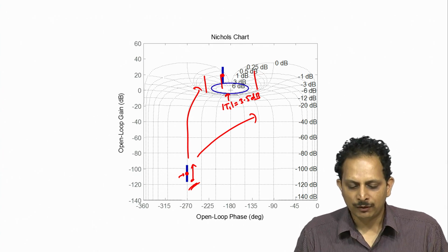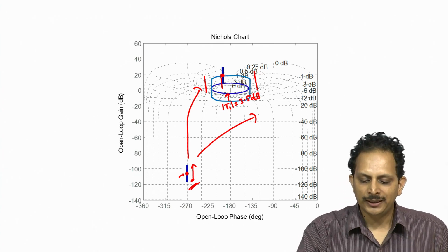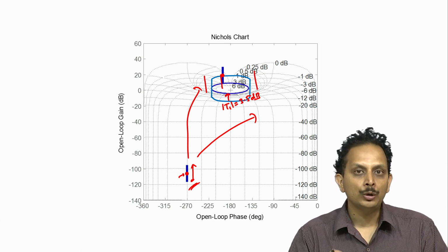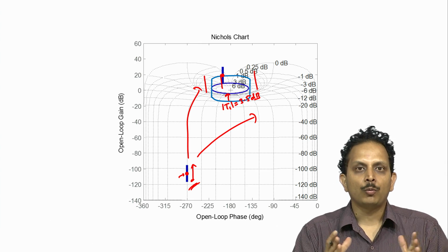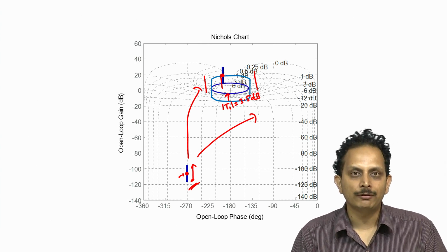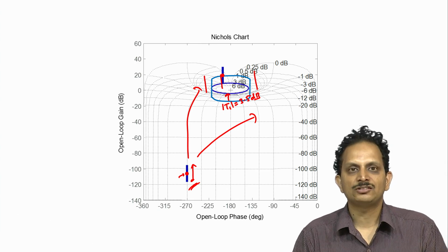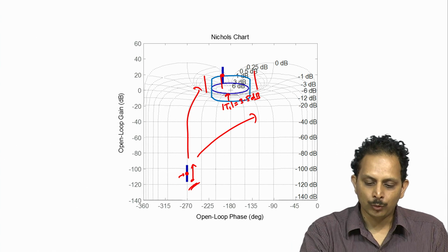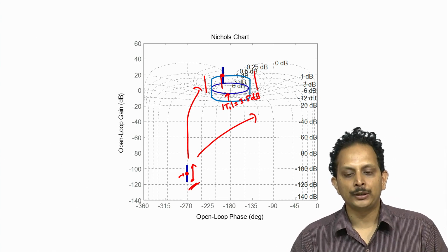And if we do that, we get this curve which essentially represents the curve on which the nominal loop gain is allowed to lie in order for the worst case loop gain to result in a transmission function T1 whose magnitude is less than or equal to 3.5 dB. So this curve once again divides the Nichols plot into 2 parts.